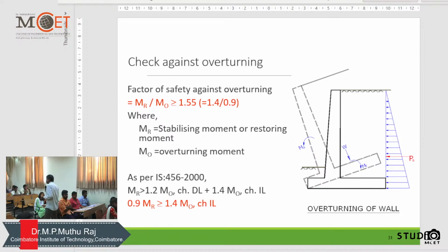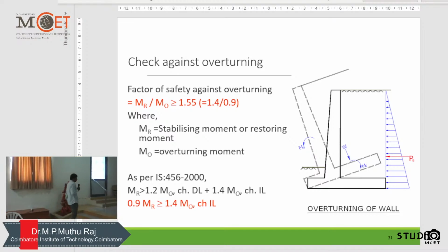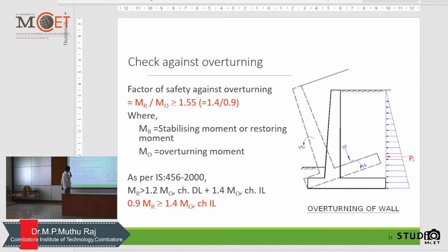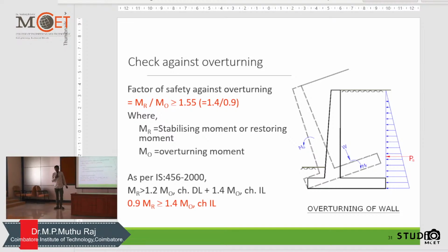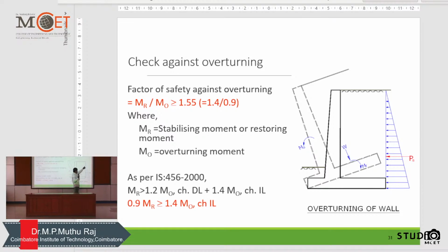So in this wall, what are the modifications that we can do so that you can go and practice with reference to the design of the geotextile reinforcement? For that, what we need to do is draw a line from this point, based on the angle of internal friction, where you are going to rest your entire retaining wall.